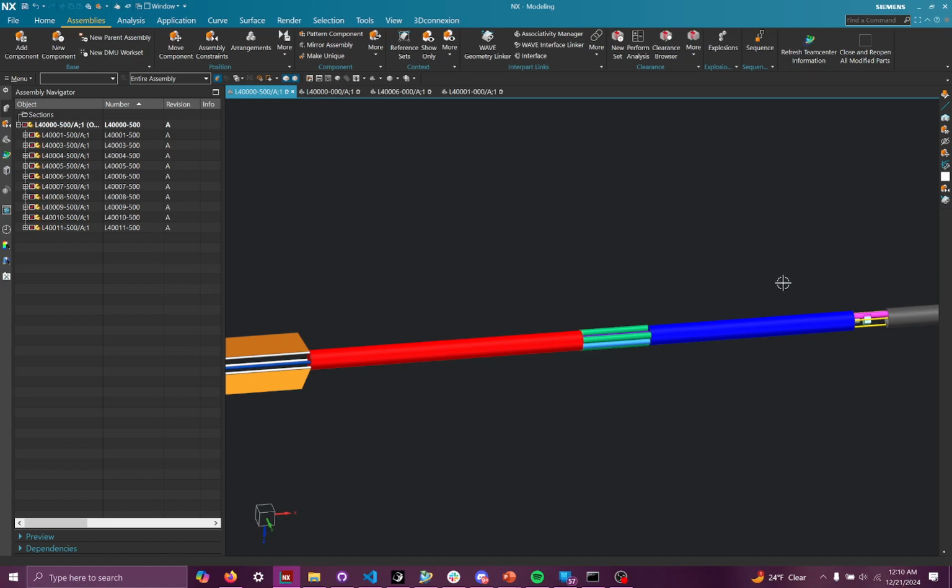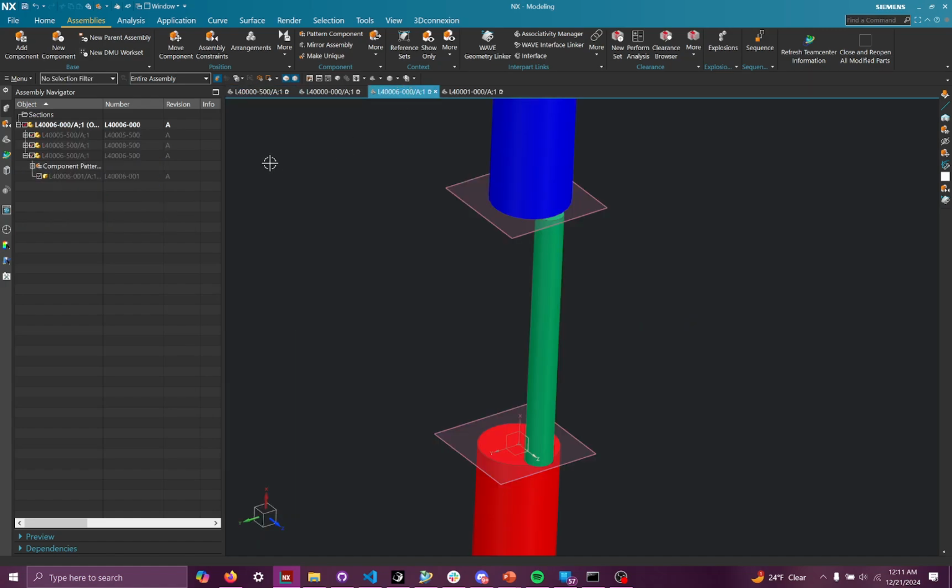Part of the reason why that happened, and why I didn't have to go into this vehicle assembly file to redo this load inner part data tool, is since I have the subassembly assembly files within the layout files for different systems making up the rocket, if I update the layout file, it automatically updates this assembly file because it is included in this layout file.